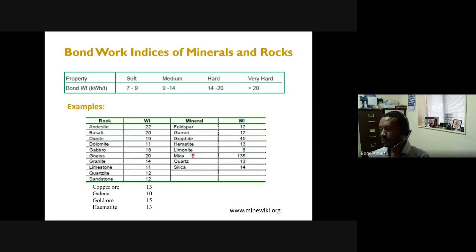Your second question was on graphite and mica. Yeah. So with graphite and mica, the issue here is not really because they're hard, it's because the method is not effective for them. Because, as I said, they're flat, they're cushioned between the balls, and they don't present themselves to be crushed very easily inside the mill. That's the main challenge for them.